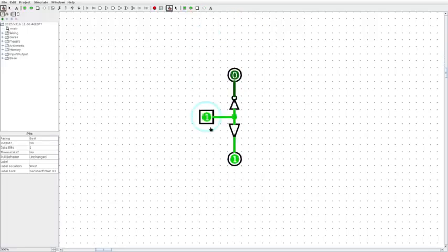Now let's go back to our original NOT gate and yes gate from before, the ones that are not controlled. Here I've connected an input pin into the inputs of both the NOT gate and the yes gate. And we can see that if the input is off, then the top output will be on, and if the input is on, then the bottom output will be on. We're essentially selecting one of these two output lines to turn on with this single input.